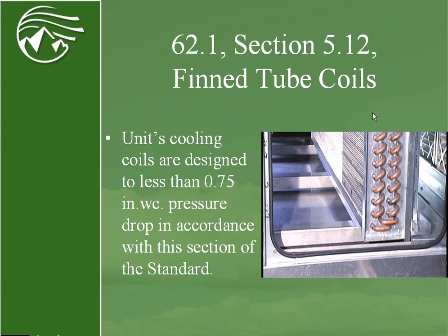Got all thin tube coils on these systems. They're designed to less than three-quarters of an inch water column pressure drop. And this unit was actually designed in accordance with 62.1. And that's basically the summary of these few slides.